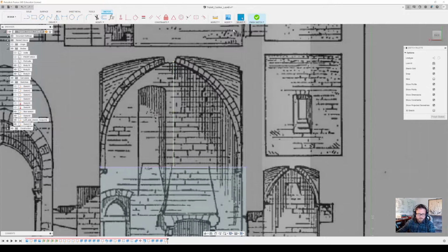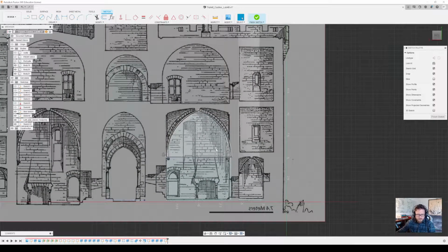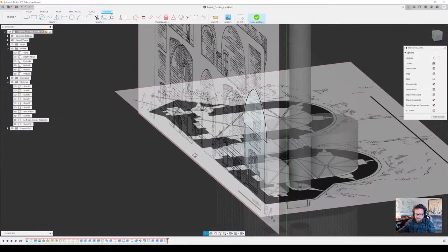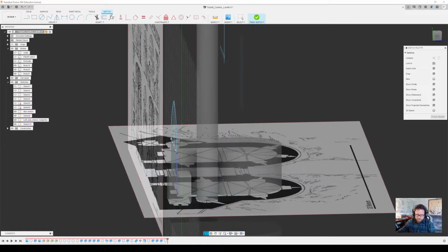Good. And this can be, I'm going to switch this to a construction line. And that gives me everything that I need to do. Make sure that they're tangent. Okay, that's useful. You can do the same thing on the opposite side or mirror it. It doesn't really matter. Sometimes it's just faster to. Okay, good. All right, we have the piece that we need for that.